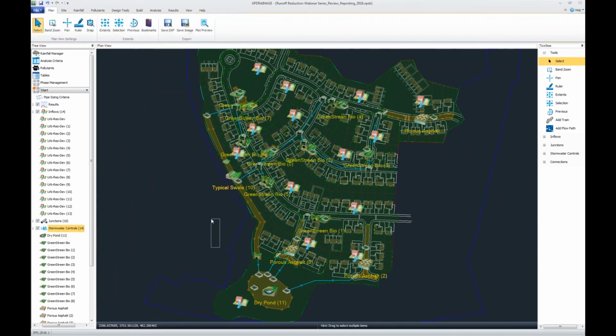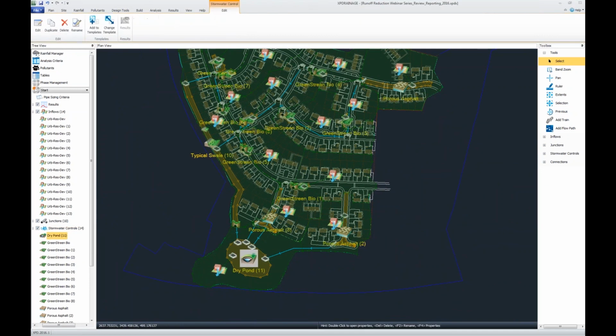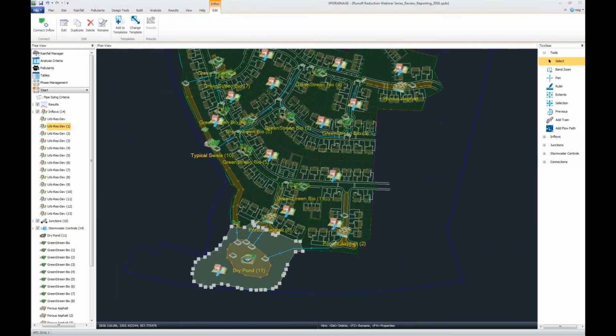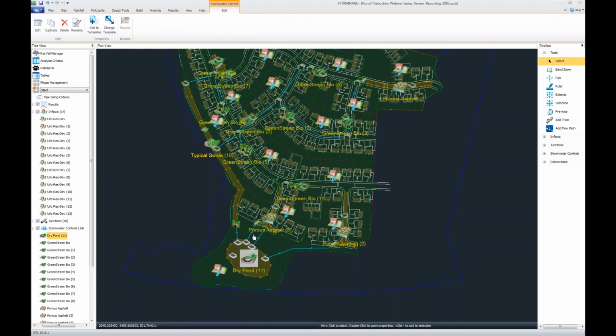So let's say this pond downstream. This pond happens to have this area draining to it, and also has 4 different inflow point sources into this pond. All of that inflow, the hydrographs that go through our system and discharge into the pond, that's all being accounted for. And then, of course, based on the outlet control, flow will leave and fill up this facility accordingly. So yes, it is taking into account all of those different systems.